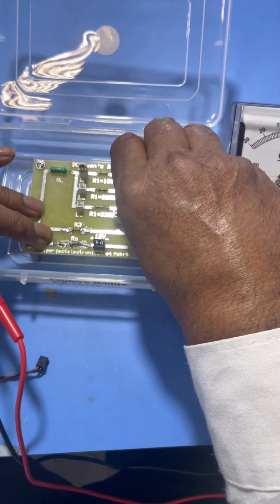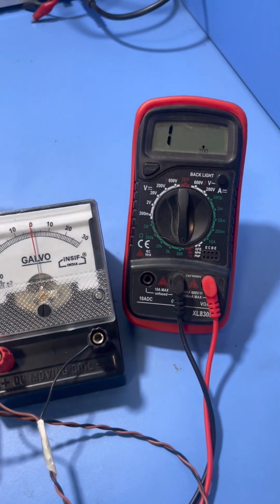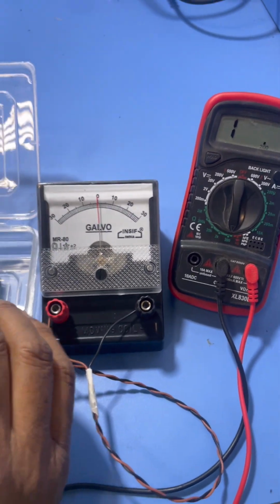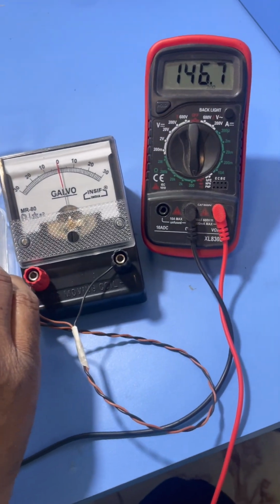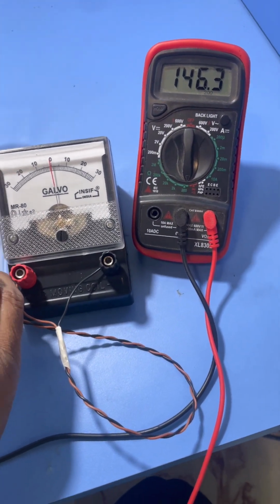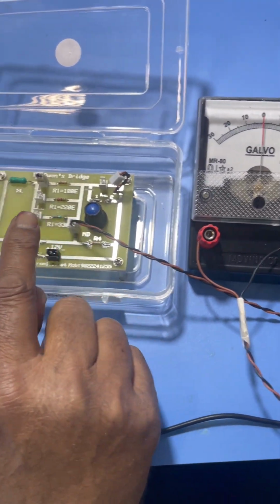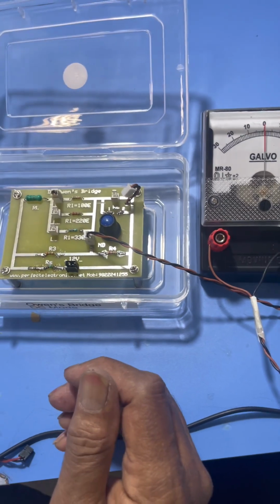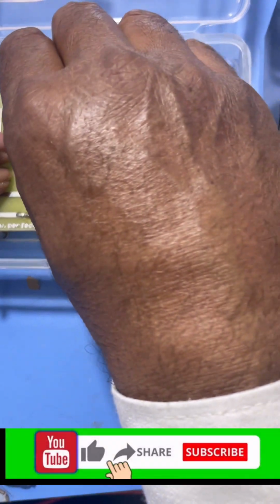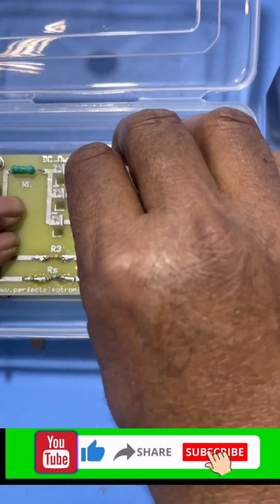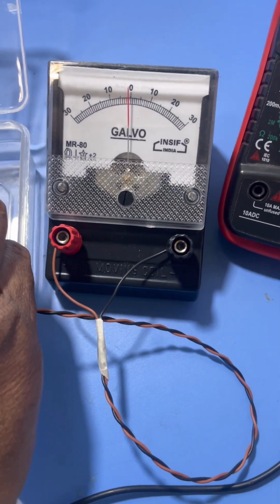and by disconnecting this port of the potentiometer here, and using the multimeter with the range of 200 ohms. I am measuring the resistance between the two points 1 and 2, and see, the total resistance is 146.2 ohms. By the use of this resistance R2 and R1, by the use of formula, internal resistance of the inductance can be determined. In similar way, we can select the resistance 220 ohms by the use of this connector here. See, we can balance the DC bridge.